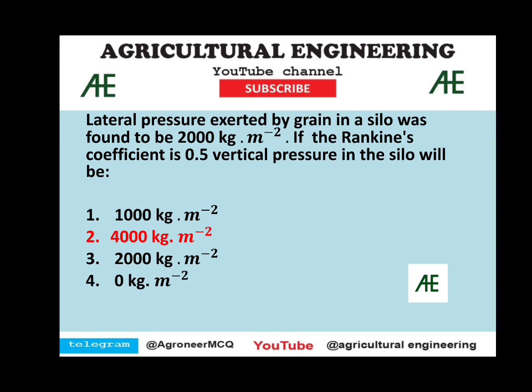Lateral pressure exerted by grain in a silo was found to be 2000 kg per meter square. If the Rankine's coefficient is 0.5, vertical pressure in the silo will be 4000 kg per meter square. So Rankine's coefficient is equal to lateral pressure divided by vertical pressure. So here vertical pressure we have to find. So vertical pressure is equal to lateral pressure divided by Rankine's coefficient. 2000 divided by 0.5, we will get 4000.